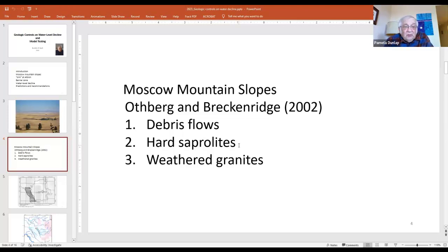Well, if you think about these hard saprolites, and you think about the number of times that the area was subjected to base level changes, remember 25 different flows coming over Pullman, each time one of those flows stopped, with the high rainfall and the humid climate, we developed the saprolite. So I believe that in the future, it might help somebody to realize that what they're reporting as saprolites are equal to the alternating hard zones identified in many of the drill logs. And to me, it helps verify that our interpretation of many depositional cycles in alluvial fans and braided streams is correct.